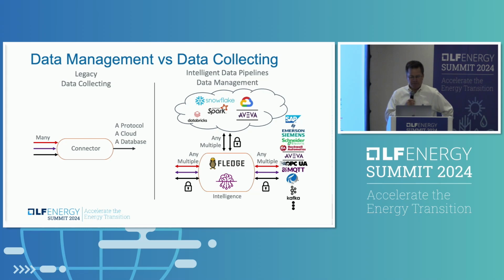All right, a little bit of background, and you probably already have a little inkling of this. How many people are familiar with tools like Kepware? Okay, or how many people use historians and then have connectors or interfaces to get data from their transformers and SCADA systems into there? So the classic 1980s architecture in OT was simply: get a connector to a protocol, get the data, and send it to this database. And that is basically the architecture you see on the left. So I can get IEC 61850, I can get Modbus, I can get DNP3, and I can send it to this database.